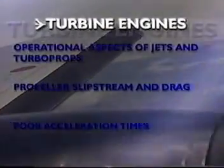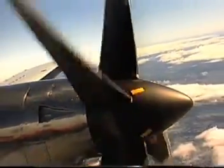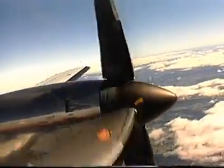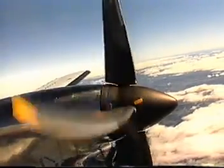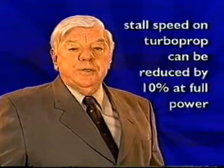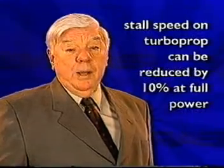Propeller slipstream and drag. It is very good not to have to compensate for the slipstream of the propeller, but nothing is for free. If you remember that the lift on a propeller aircraft is greatly influenced by the lift generated by the propeller slipstream on the wing area, you will realize that it is possible to vary lift rapidly by simply reducing or adding power. A typical approach power-off stall speed can be reduced by 10% at full power, a feature that can be smartly used to overcome many last-minute mistakes.